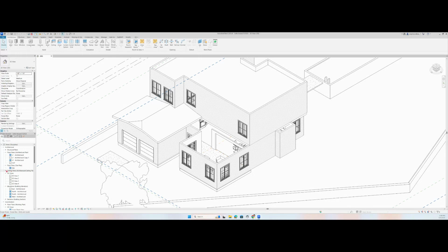I have a plus sign, so I need to click on this plus sign. This one will deploy level one ceiling and level two ceiling. So let's work on level one ceiling. By the way, you can also right click, rename, and I can put here instead of architectural, I'm going to put ceiling. Still under the architectural discipline, but let's change it for ceiling.